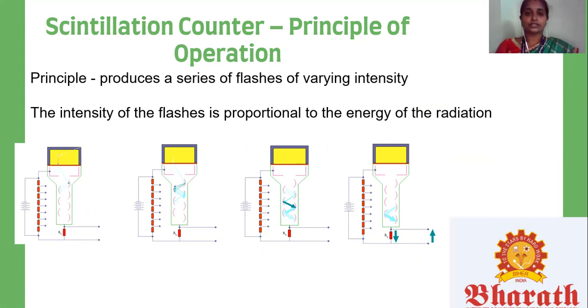These secondary electrons are attracted to and strike a second dynode, releasing more electrons. This process occurs in the photomultiplier tube. Each subsequent dynode impact releases further electrons, and so there is a current amplifying effect at each dynode stage. Each stage is at a higher potential than the previous to provide the accelerating field.